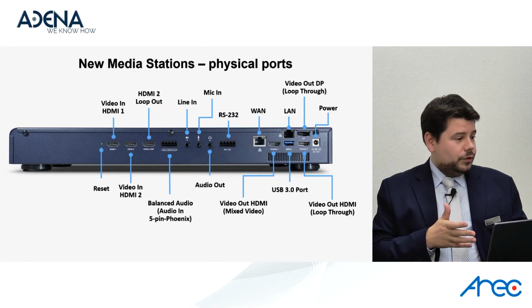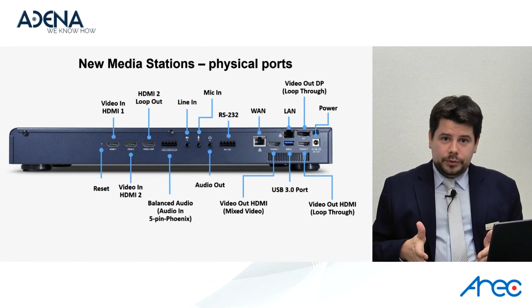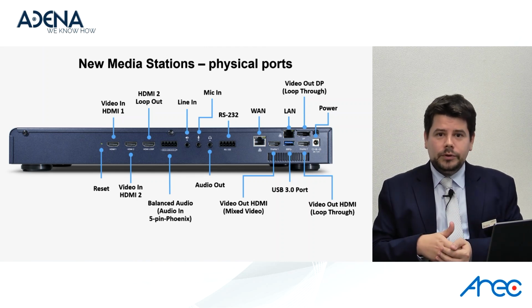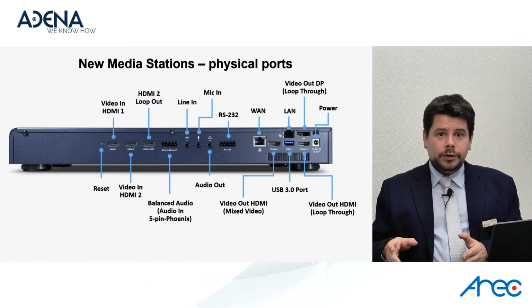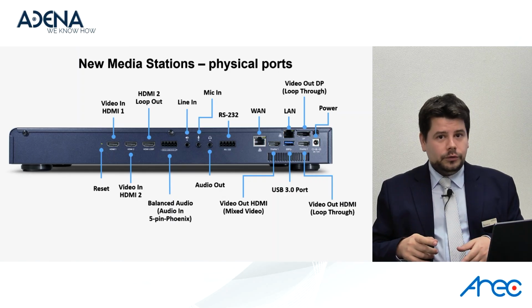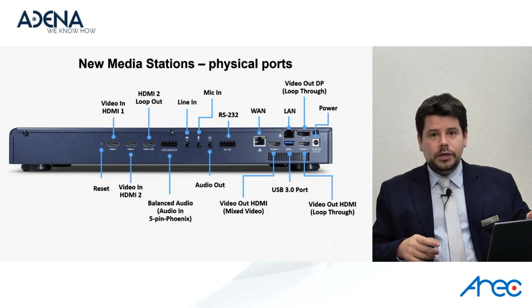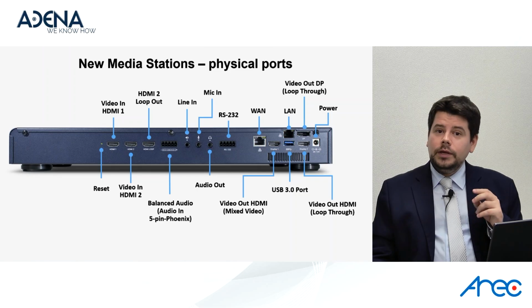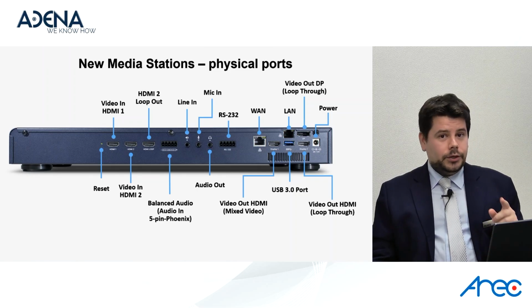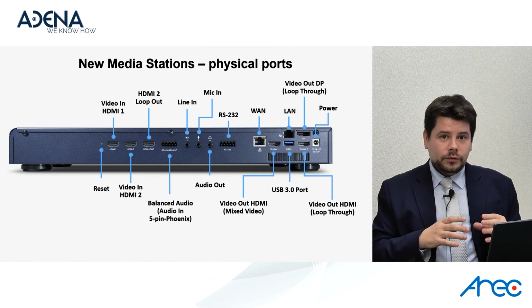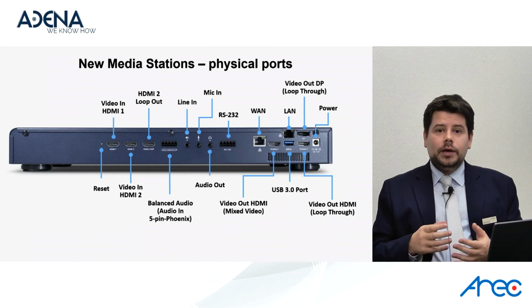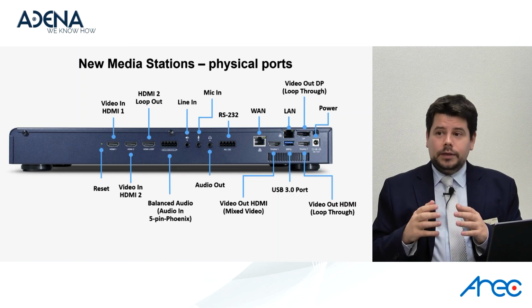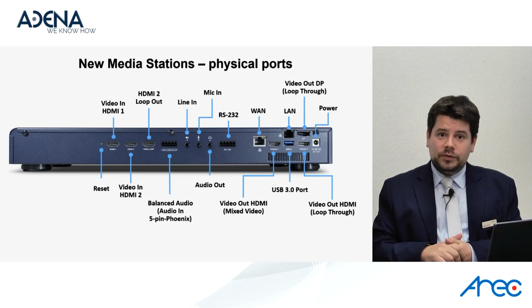After that, there is also a number of audio inputs: the Phoenix balanced input, the line and mic input. You can also connect audio through network, not only Dante, but you can also do RTSP, RTMP, RTP, and other protocols that are supported. Then there is also the RS-232. You can send commands through this serial port to the device, or you can also use TCP/IP commands or HTTP API commands. The commands list is public on our website as well, if you want to take a look.